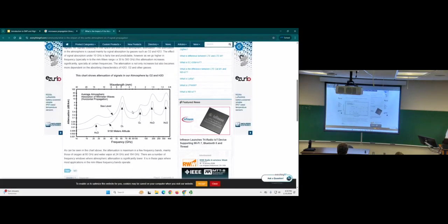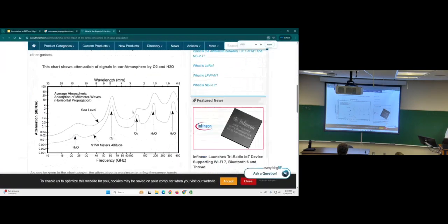There we go. So this, starting at around 10 gigahertz, is attenuation, so this is energy lost over distance, bigger number equals bad. And of course, it's in decibels per kilometer. A loss of just 3 decibels is half your power gone, like that. So keep that in mind. You can start seeing it gets a little ridiculous per kilometer at certain points.